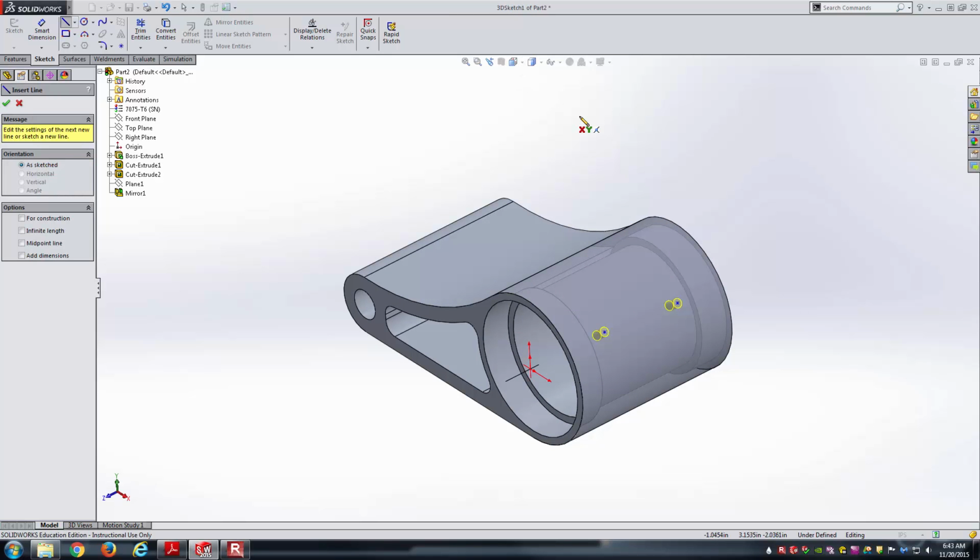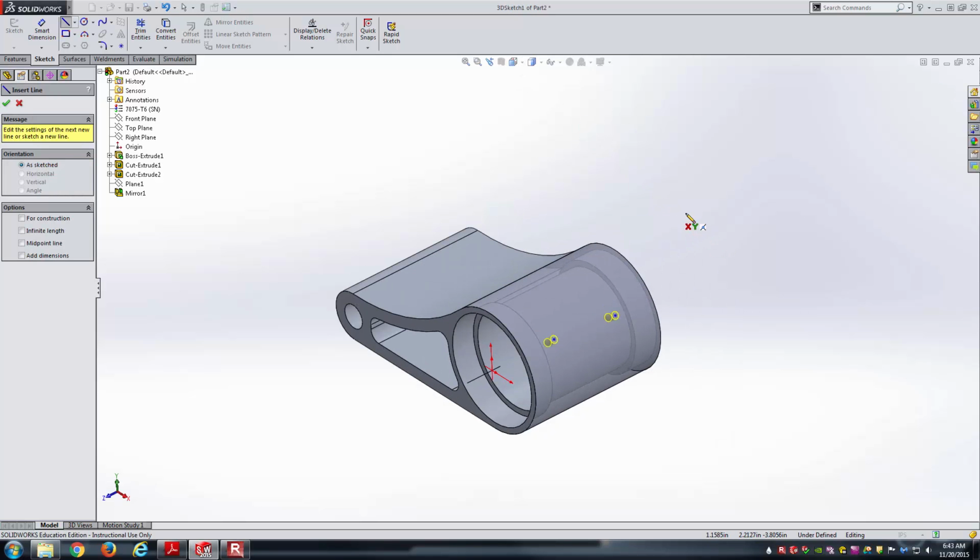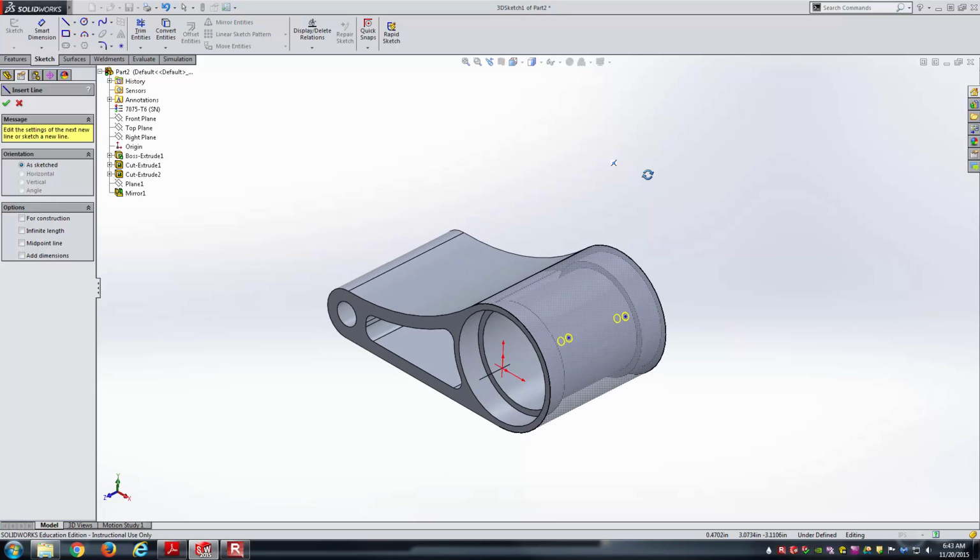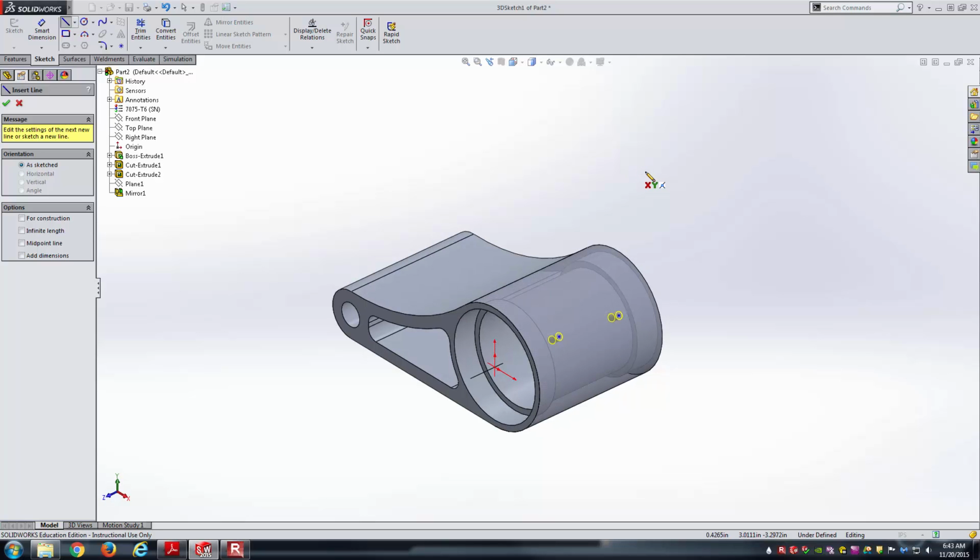And so what I'm going to do is go ahead and create a line. And so here I'm in a 3D sketch, that's why you see the little pencil and the XY. And so this means I would be sketching parallel to the XY plane. Here I need to draw a line in the Z direction, so I need to make sure that I have something other than XY. So here's YZ. I just manipulated that by hitting the Tab key, which oscillates between these.